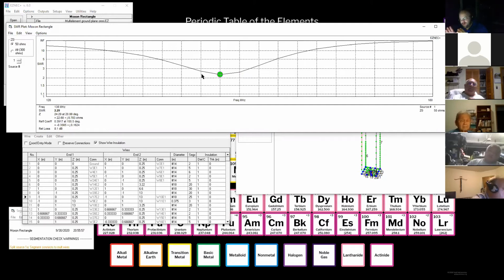So when we're talking about recommended settings, there are times where you're going to change the diameter. Choose the diameter that you're going to build the antenna out of and run with it. When you get more comfortable with the program and you're trying to balance out complex designs, then you can start to get a little jiggy with it. But start easy. If you can, keep all the diameters the same, because in the program, as in real life, the diameter of your elements can make a huge difference.